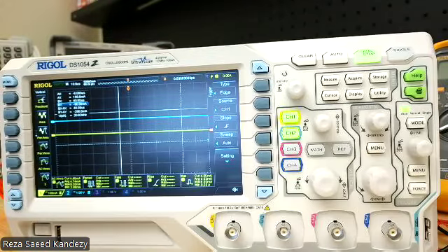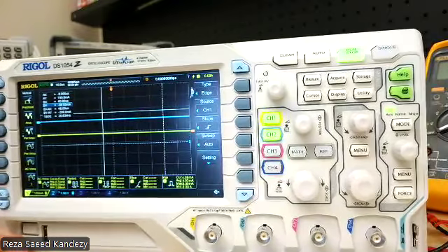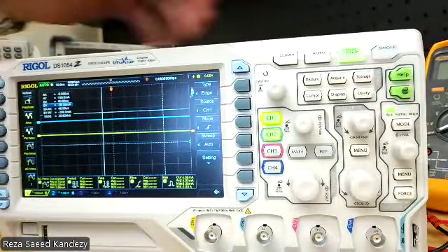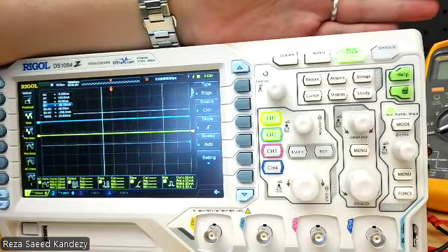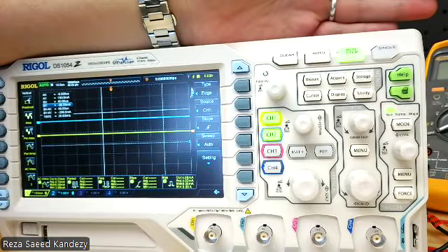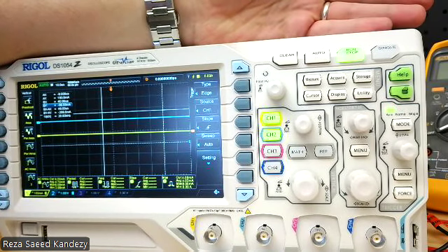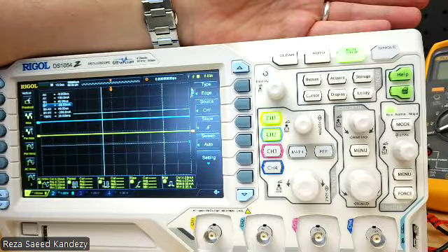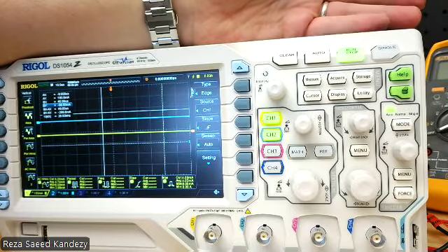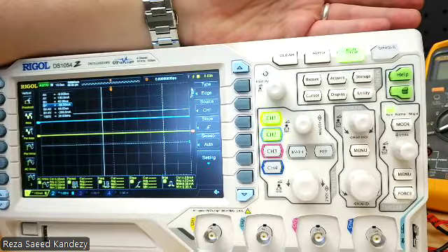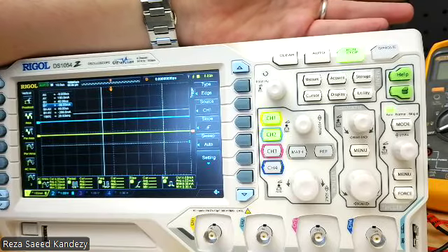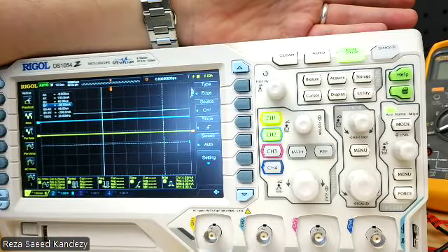Now, let's talk about the last part that we want to explain for the oscilloscope, which is the trigger menu. The trigger menu is basically what stabilizes your waveform. Without a trigger, the scope would just keep redrawing the signal randomly, and you see a mess. So you can trigger on any of the 4 channels or on the external input. That is the option this oscilloscope gives you.